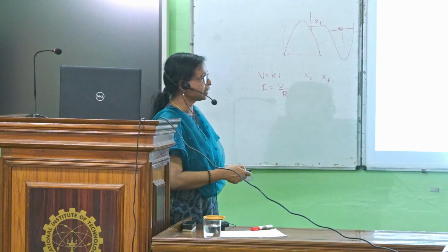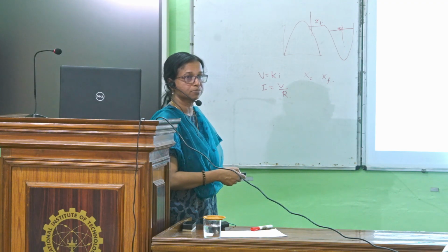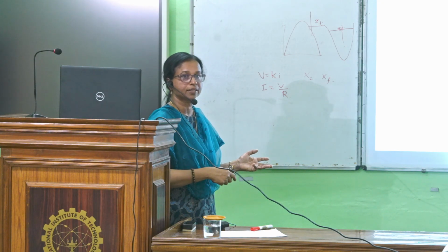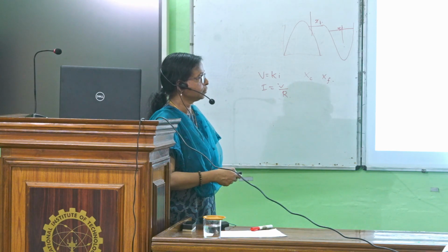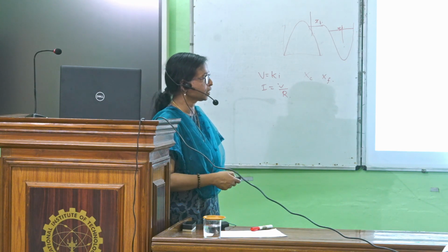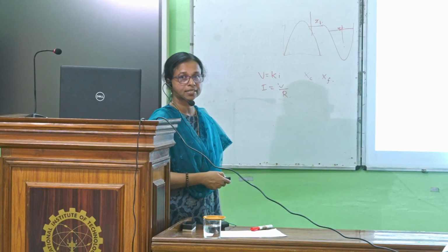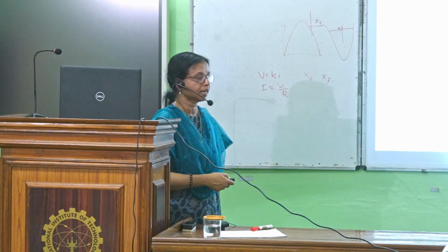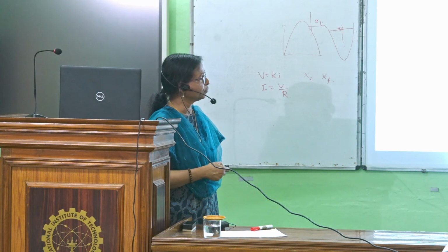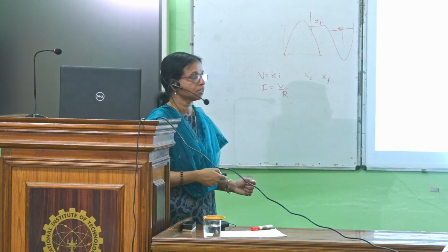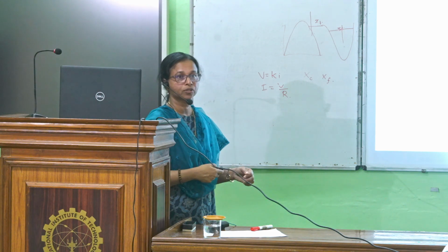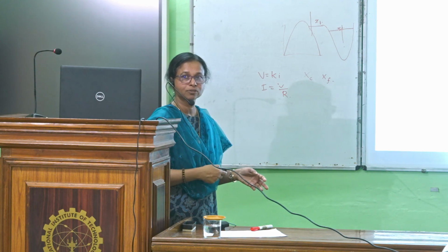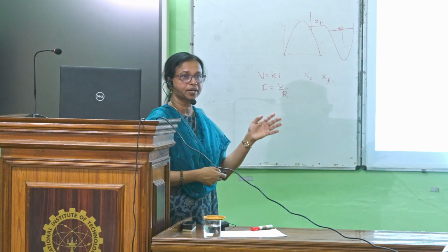So from the condition we are giving at the downstream side or upstream side, but it's not the profile that you can assume whether you have to give upstream side or downstream side. Suppose you are computing a backwater profile, then on the downstream side, you will be knowing the depth of flow at the control section, then compute Y2. So that is the process. Based on the standard step method, you have to compute Y2. When you compute Y2, the assumed value should match with your computed value. So there you can give some tolerance and finally find out Y2.